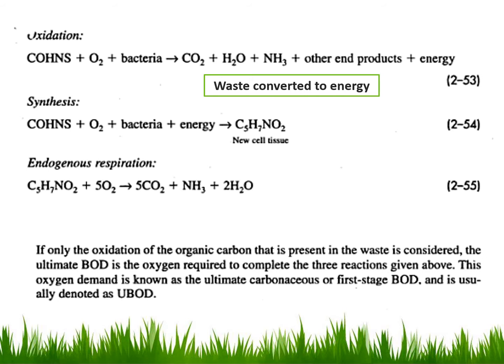So link it with the UBOD, ultimate BOD. Ultimate BOD is the combination of all the requirements of oxygen. This is the oxygen requirement. This is another oxygen requirement. So combining all these requirements is going to describe the overall oxygen requirement for the final decomposition of the organic content. That is leading us to a term called ultimate BOD.